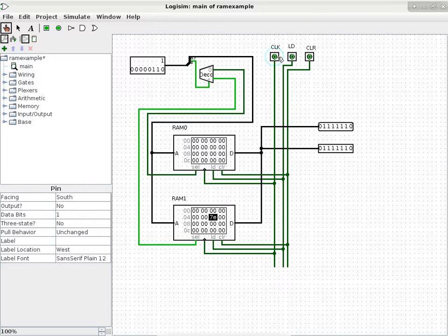What about the clocking one? That is the most significant one. Because the clocking, when we transition clock from 0 to a 1, that's from the processor's perspective. Does the RAM chip actually respond instantaneously? Nope, it does not. It takes a certain amount of time for the RAM chip to sample the data line, copy the content on the data line into its content. It takes a certain amount of time. Is that okay so far? So that's basically what is determining the speed of memory.